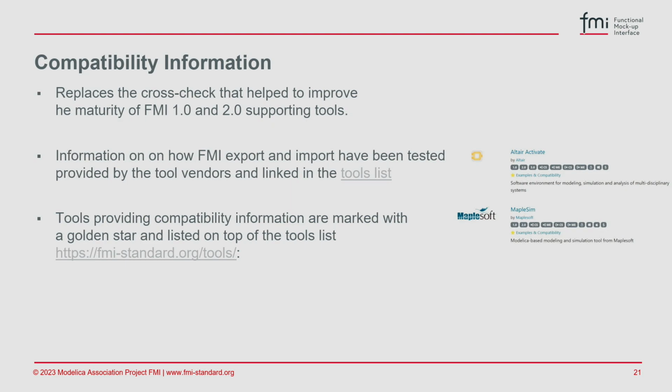And this is not about black and white, so then you have to dig into the system, look into the frequency behavior of the different FMUs and so on. So FMI does not solve all of the numerical simulation problems of the world, but what we more want to exclude is really the obvious faults. For example, if you look at the XML, you can decide is this right or is this wrong.